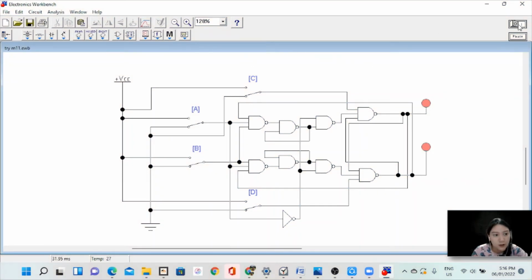So as I turn on the simulation, all the switches are connected to the ground. So the first thing that we should do is compare this to our truth table. If the clock is at 0, and if the toggle is at 0 or is connected to the ground, it means that our output is on hold.